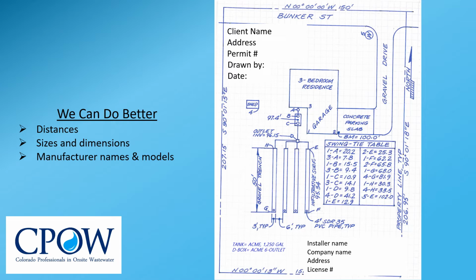The slide provides an example of a record drawing whereby all components can be easily located. Note how distances are provided in a simple chart. Tank size, permit number, installer, owner are also provided on this sheet. If necessary, a separate sheet providing any other required data can also be attached, such as component depths, size, or other pertinent product information. Note how in this drawing we are able to locate the distribution box, which is located near the header of the soil treatment area.